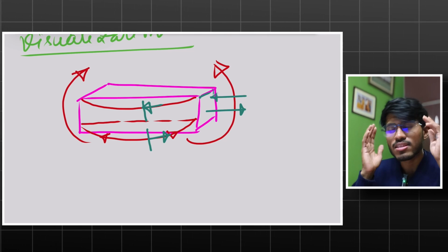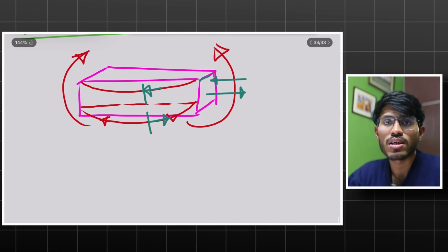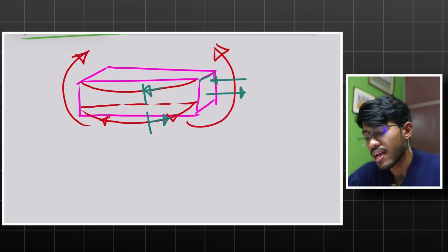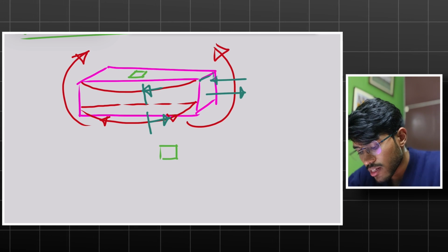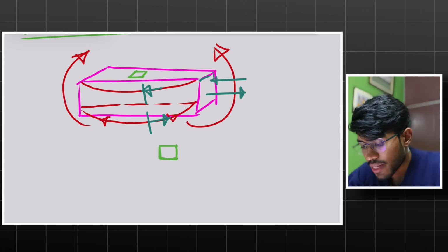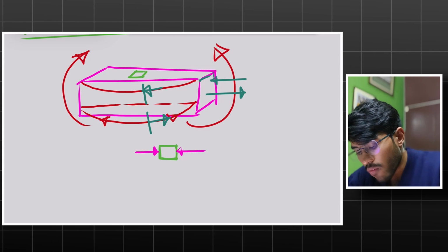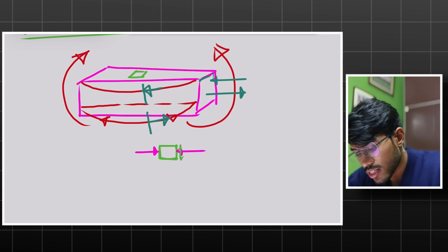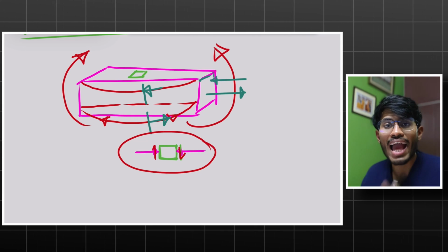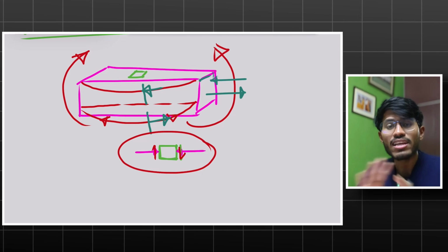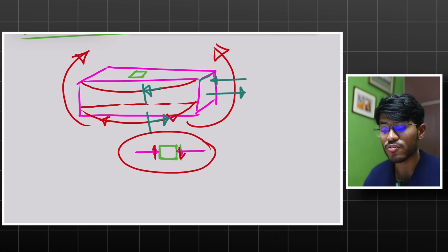This is very important, and more so for the machine design subject, because there, if you have to draw the Mohr circle or find the principal stresses, they will say, take an element like this and draw the stress state for it. That means you have to say, here I will have this type of compression and this type of shear stress. And how can you draw this if you don't know how the bending stress actually acts? What is the direction? And again, don't memorize these things. They have to be understood by intuition.